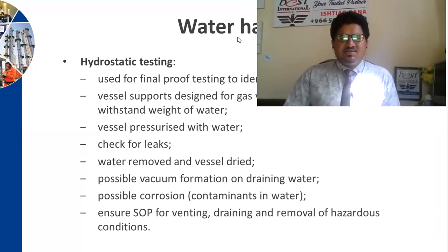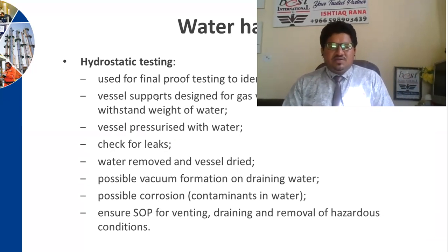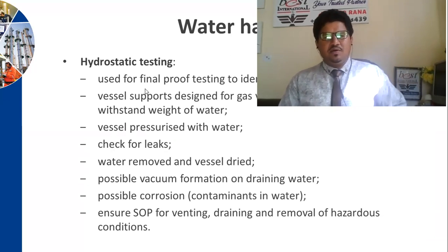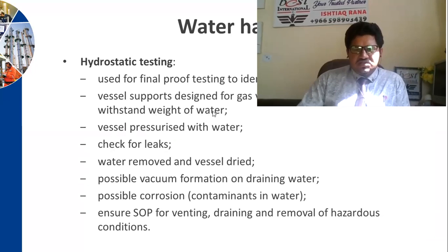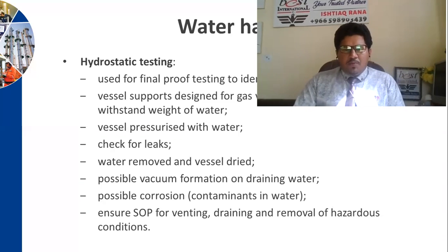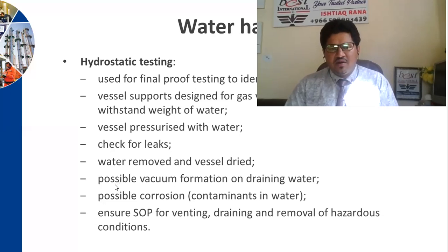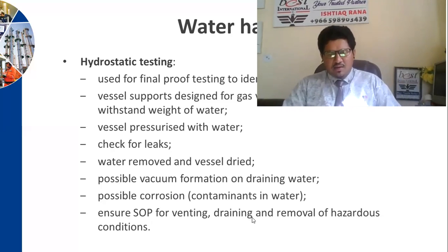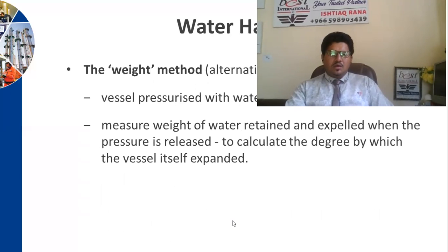Now, hydrostatic testing. This is again one of the hazards we need to consider during hydro testing. It is used for final proof testing to identify leaks. Vessel supports are designed for gas, and vessels may not be designed to withstand the weight of the water. The vessel is pressurized with water, checked for leaks, then water is removed and the vessel dried, with possible vacuum formation and also possible corrosion. Contaminants are removed. Ensure SOPs for venting, draining, and wet conditions or removal of hazardous conditions are there.